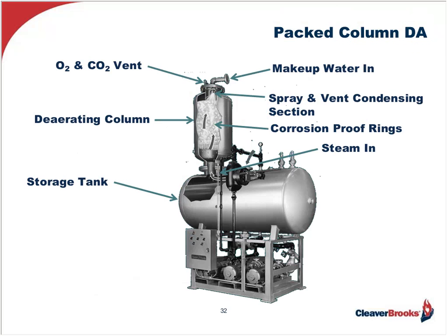Now, taking a closer look, it's plainly obvious how it got its name with the deaerating column positioned on top of the tank and packed with rings, normally of stainless steel, and they're providing the medium for lessening the surface tension of the water while also providing an excellent means of commingling the water with the steam for outstanding counterflow heat transfer and heating, after which the corrosive gases, the O2 and the CO2, release to atmosphere.